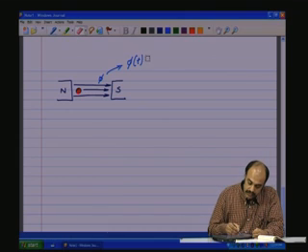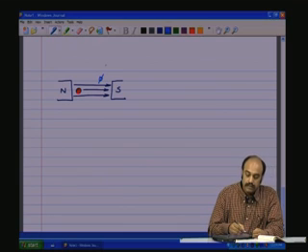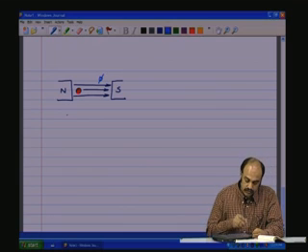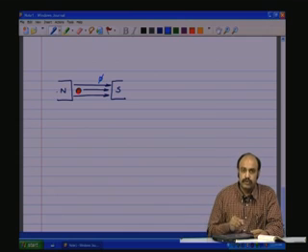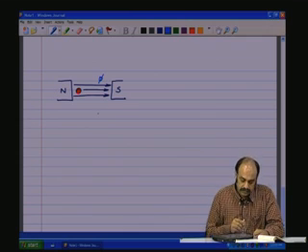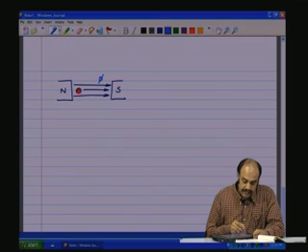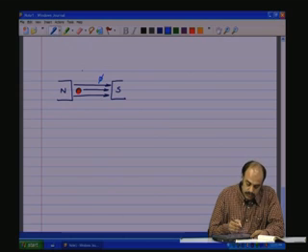The other way is to have flux fixed. The flux amplitude is fixed. You have permanent magnets, north and south pole, and therefore, the distance between them is also fixed, and therefore, the flux phi is fixed. Under such a condition, the only way that you can have a change in flux is if the conductor moves.